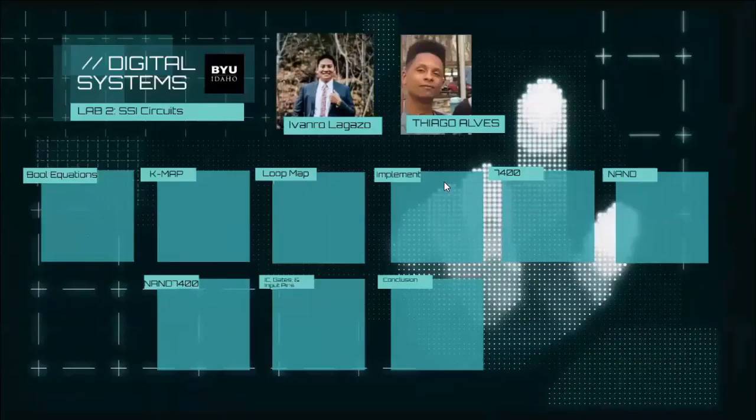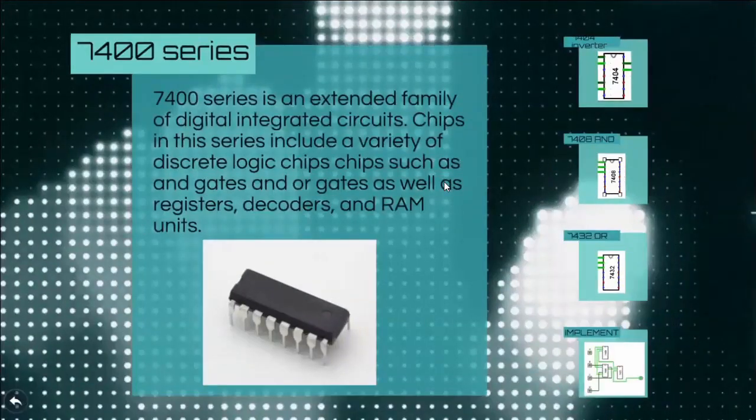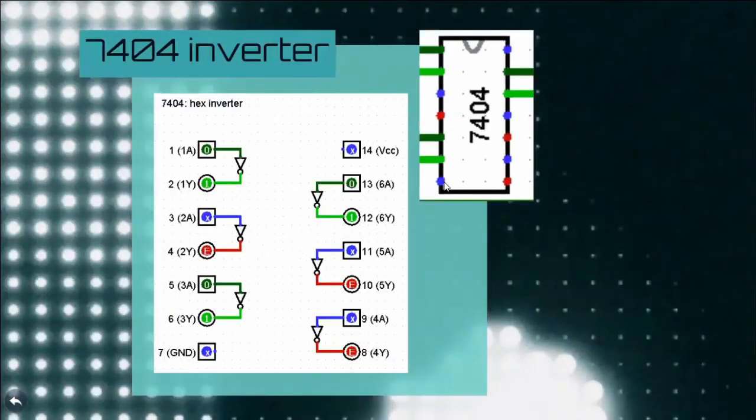Now we're going to talk about a family of integrated circuits, or chips, the 7400 series. This is an extended family of digital integrated circuits. Chips in this series include a variety of discrete logic chips, such as AND gates, NOR gates, as well as registers, decoders, and RAM units. So we have, for example, the 7404 that has a set of inverters inside. So we can take this chip and use the inverters that are in it.